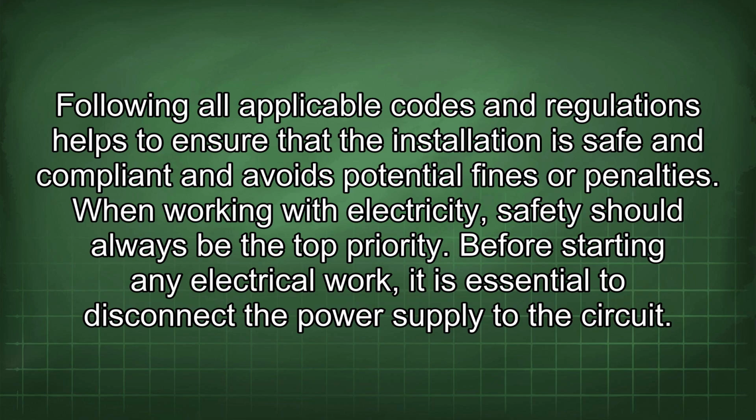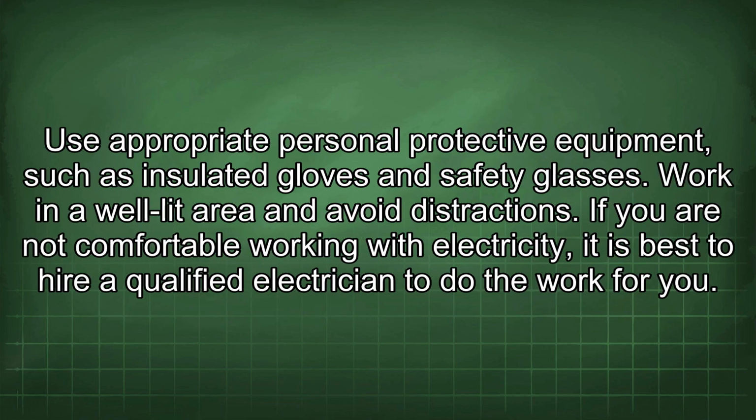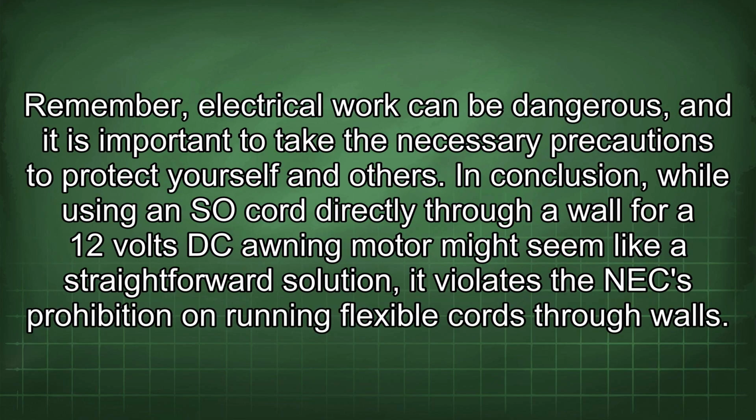Before starting any electrical work, it is essential to disconnect the power supply to the circuit. Use appropriate personal protective equipment, such as insulated gloves and safety glasses. Work in a well-lit area and avoid distractions. If you are not comfortable working with electricity, it is best to hire a qualified electrician to do the work for you. Remember, electrical work can be dangerous, and it is important to take the necessary precautions to protect yourself and others.